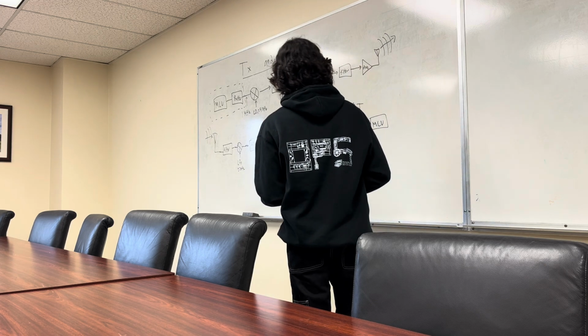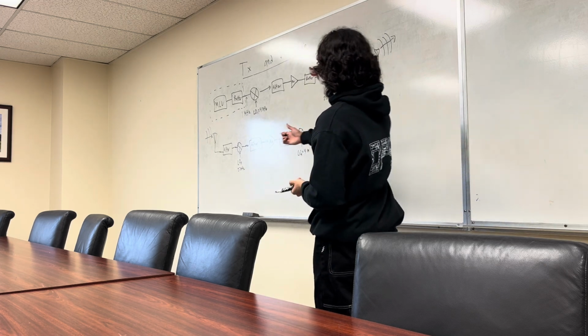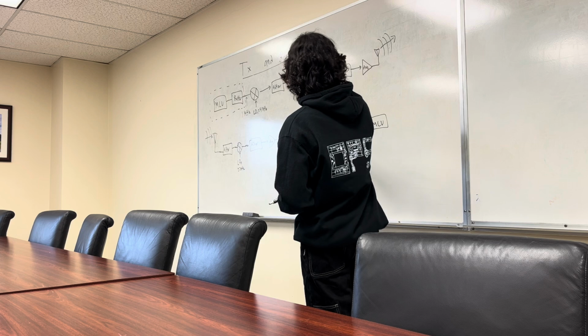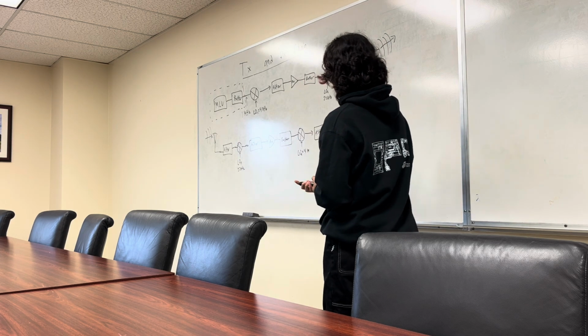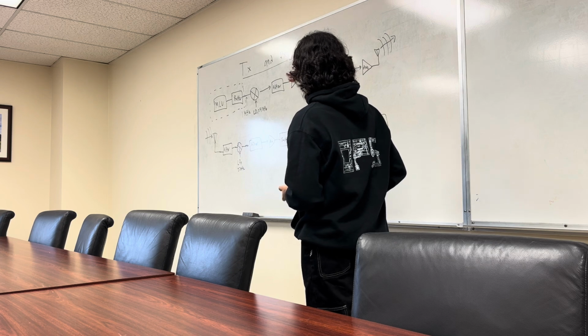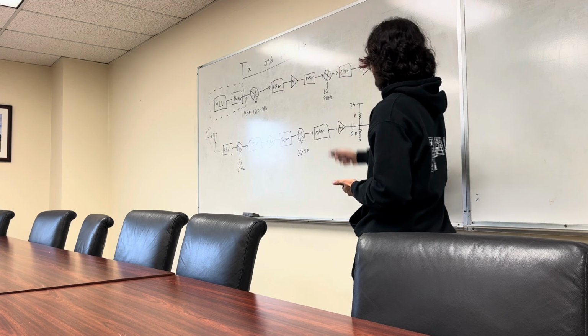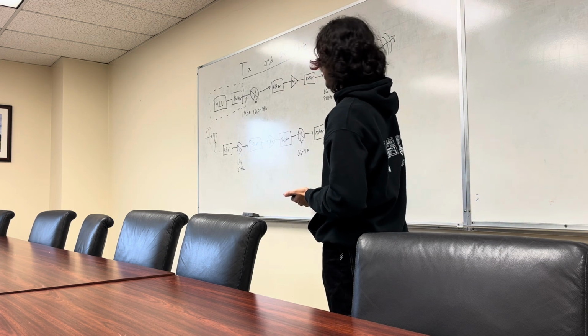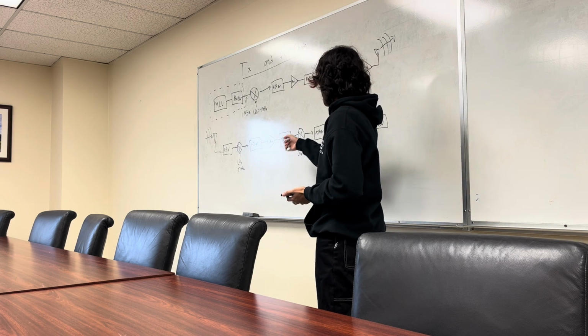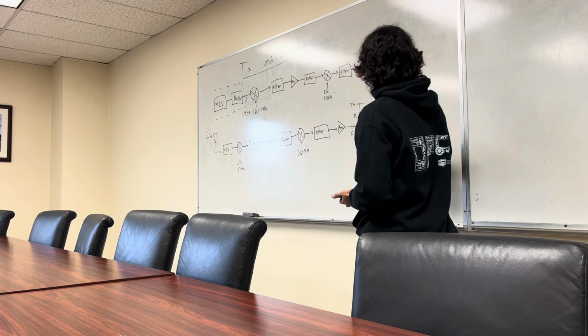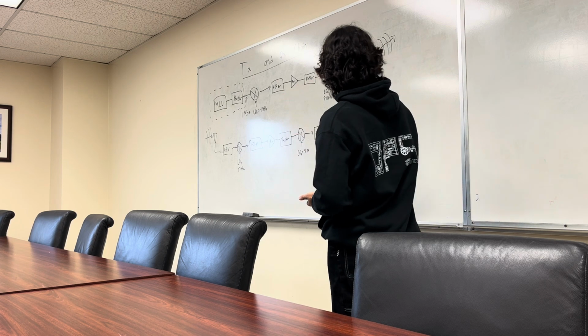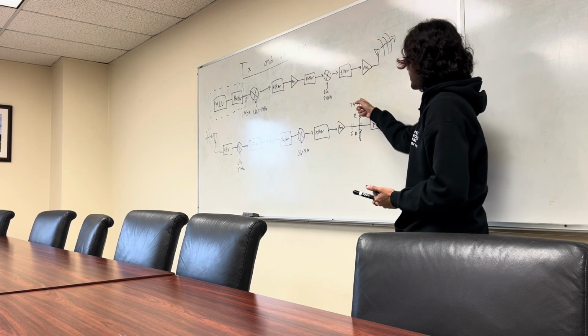Okay, cool. So this front part, our front end, is pretty much just a mirror image of this, effectively. I've excluded the LNA for the time being because we'll talk about that later, but this is a very rudimentary approximation, right? So it's a 27 megahertz filter, 5 megahertz, 1 megahertz. Over here, you're 5, 27. This part's tricky, and so is that part, right? Why do we have this network here?